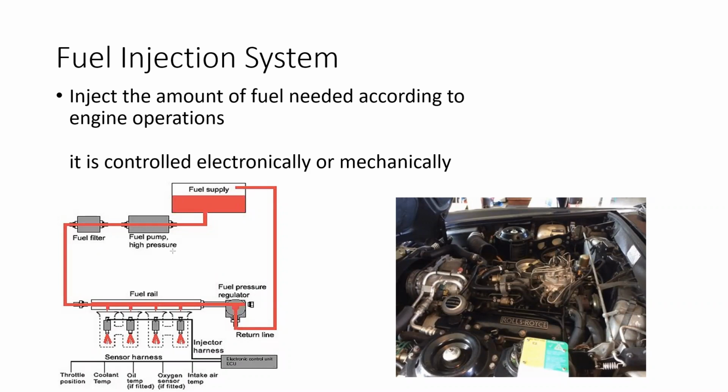It measures how much vacuum there is in the manifold, and based on that vacuum it regulates the fuel at the necessary value for that particular instant. If it is getting more fuel than that, it will cut and return the fuel back to the fuel tank, right?